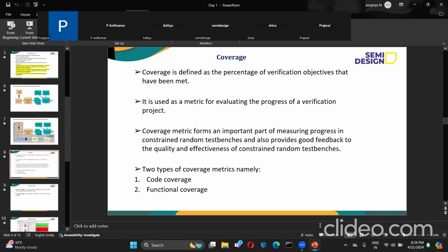All test cases are passing. There are 100 test cases in regression, and all of them are passing. You have uploaded and extracted the coverage, but coverage is still showing 80%. Mostly functional coverage will be less. Suppose if functional coverage is 40%, the toggle coverage will be around 60 to 70%, because toggle coverage will have more bins and it will hit more compared to functional coverage.